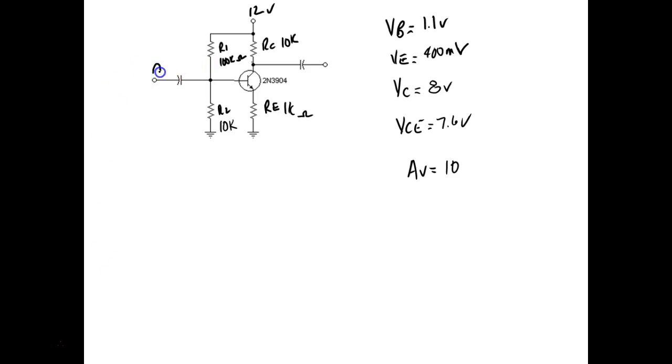So AC over here. Over here, if this is 0, that same AC signal is riding on top of DC. So what it's doing is adding, subtracting from the DC base voltage. If it adds and subtracts from the DC base voltage, it's going to add and subtract over here on your emitter resistor, right? Which changes the current flow, which just causes the output flow.